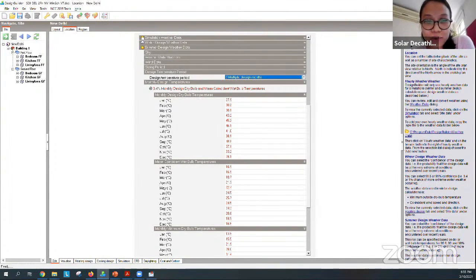So adding more regarding the weather file. The weather file that DesignBuilder is using is the TMY file, which is the typical meteorological year file. You can also use an AMY file, which is the actual meteorological year data. If you have a weather station near your location and you have data from there, you can use it directly by converting it into an EPW file and then importing it in DesignBuilder. So that's one option where you can get the nearest weather conditions as per your location.